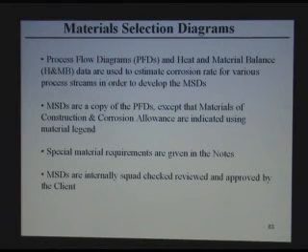We indicate special material requirements. For example, if you have wet H2S, we indicate heat treatment. We indicate that material should be tested for heat resistance or some other special requirements. We indicate maximum velocities to avoid corrosion and erosion, for example in amine services. And these material diagrams are a very important document for any project. They are internally checked and finally approved by the client for implementation.